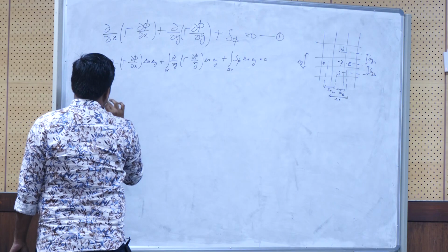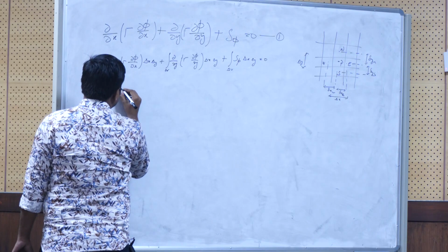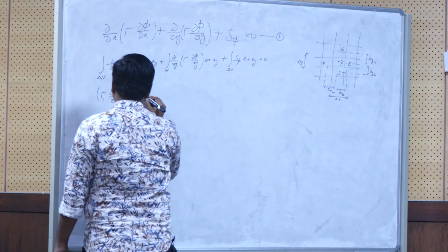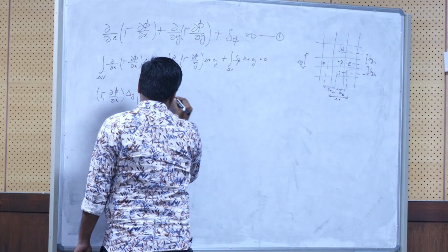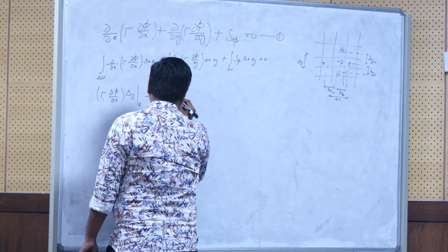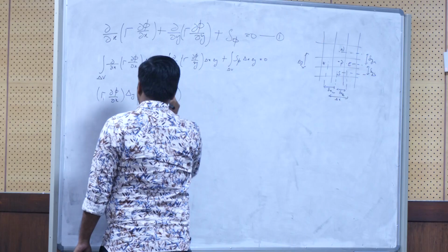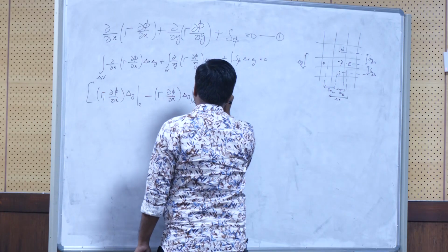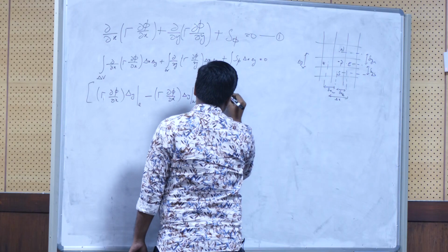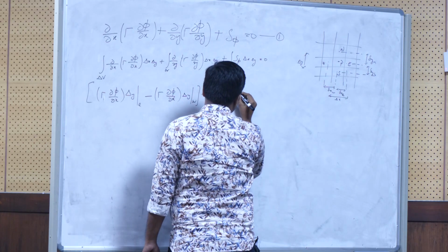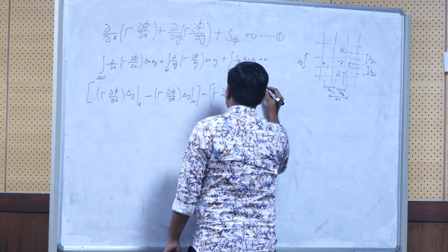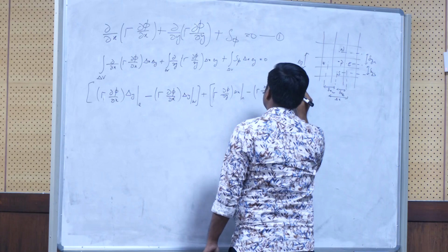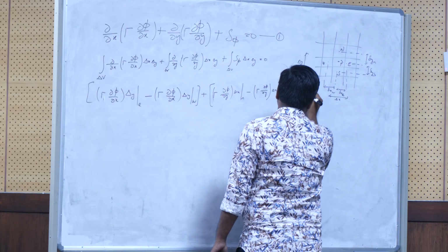Now we integrate that and get, finally, lambda e times lambda dou phi by dou x into del y from e, minus lambda dou phi by dou x del y from w, plus lambda dou phi by dou y del x from north, minus lambda dou phi by dou y del x from south, and we write the source term as capital phi into del v equal to 0.